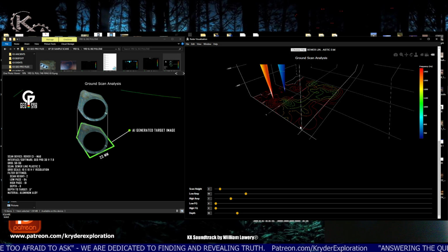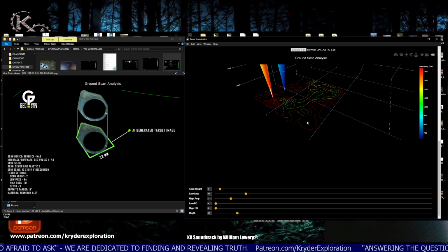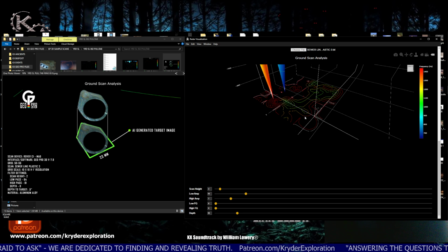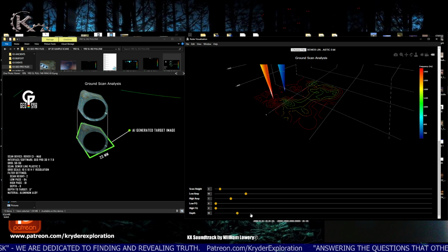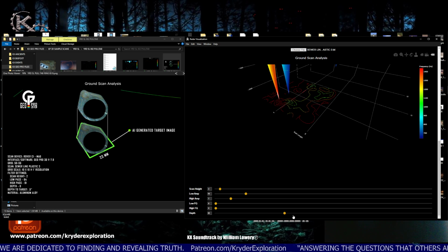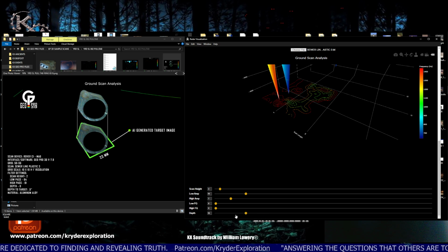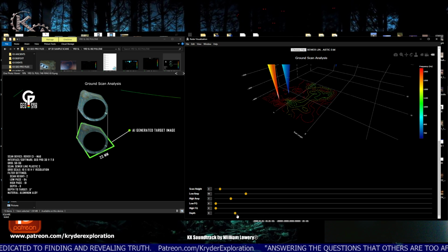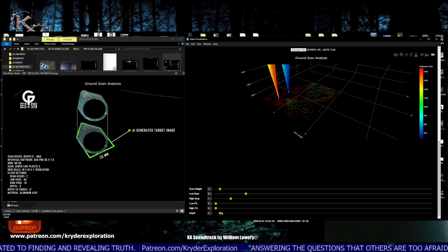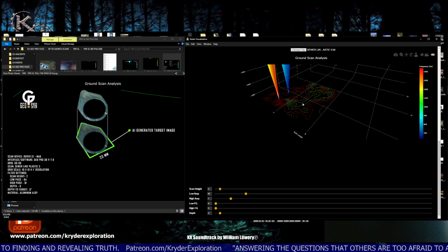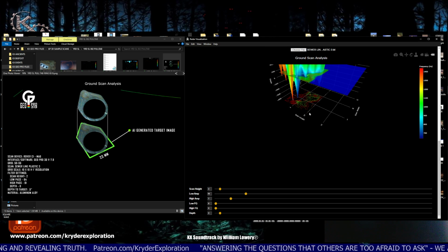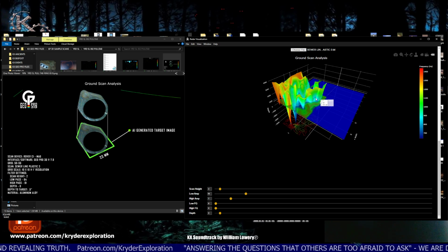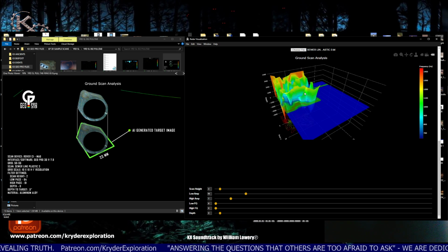And this line goes around that aluminum object that's laying here. It's affecting the field, making a hole in the field. But as you can see, we can run our depth up and down to look at our ditch and the structure of our ditch, and it'll show up different details of it. And potentially this is actually moisture that's leaking from the pipe and making a plume area here. So, you kind of get the gist of what to do with the data.